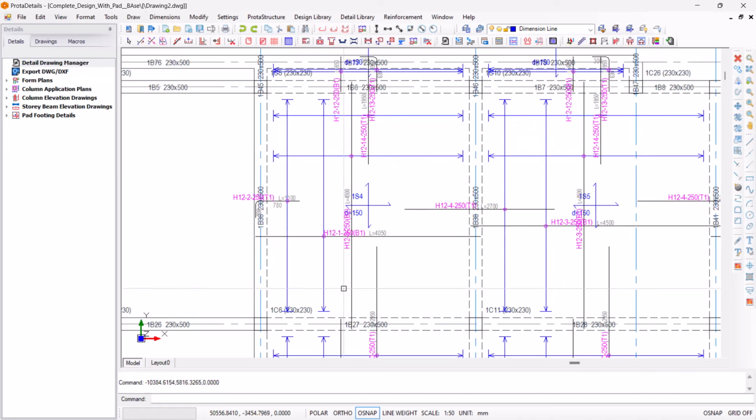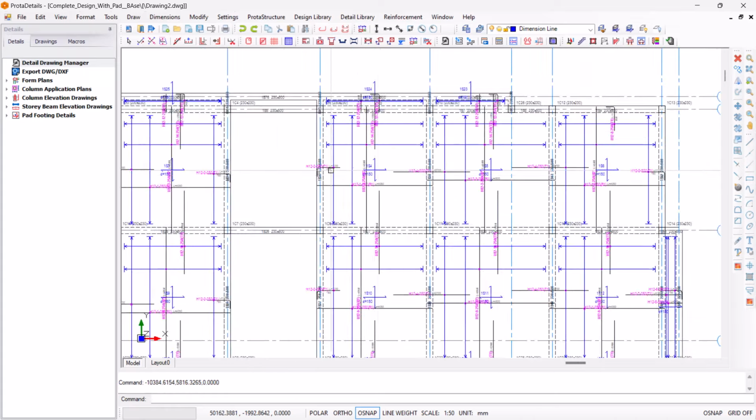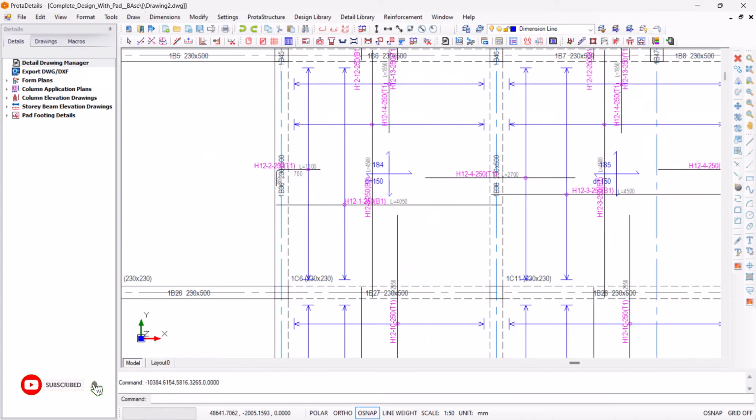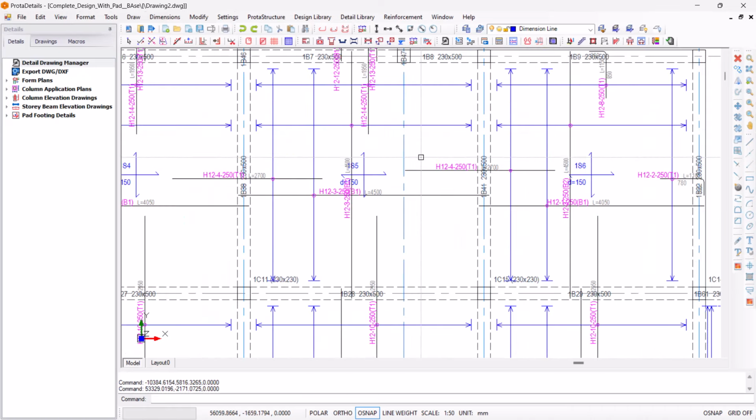This is the bottom bar here. This is on the shorter span, which is our B1. This is on the longer span, which is our B2. This is the returning top bar. This is the top bar countering the hogging moment at this support span. This is also another top bar for our hogging moment.